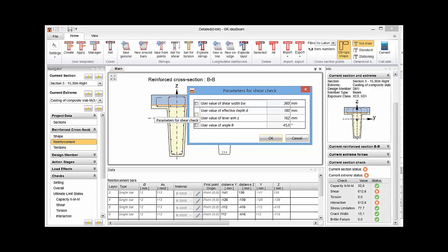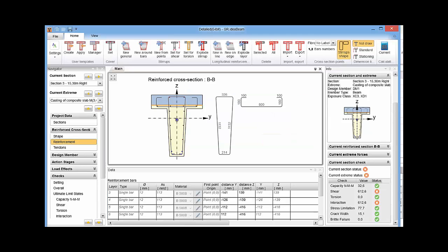Check on here, which is always possible, and then we disregard the flexure, which in fact, in my opinion, the check of shear should not be directly related to lever arm from flexure, because we have different distance of top and bottom part, or top and bottom stringer defined by reinforcement anyway.